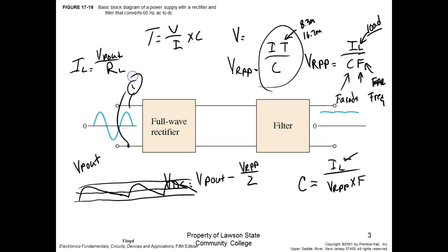Measuring our RMS voltage in, then come up and calculate V peak. So V peak would be VRMS divided by 0.707. Then I'm going to come over here and measure my DC. Make sure you put your meter on DC over here, and over there make sure your meter's on AC. And then it should measure less, but not that much less, than what you calculated. That makes sense? That's a good rule of thumb without having to do all the math. Okay?